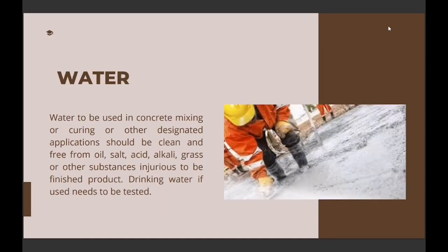Water. Water to be used in concrete mixing or curing or other designated applications should be clean and free from oil, salt, acid, alkali, grass, or other substances injurious to the finished product. Drinking water, if used, needs to be tested.